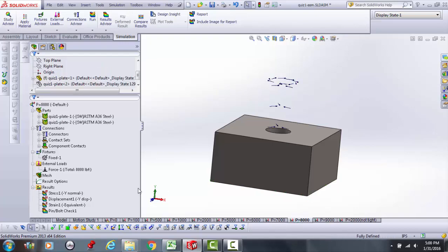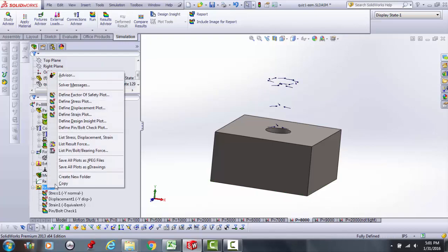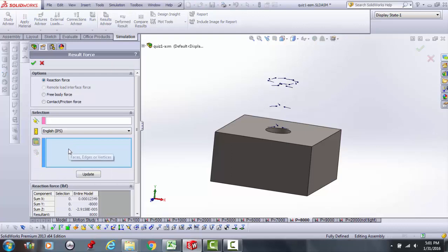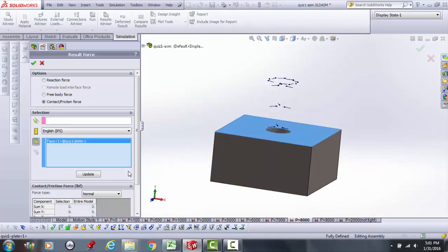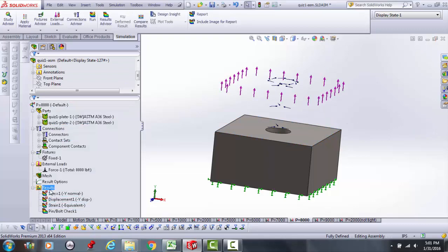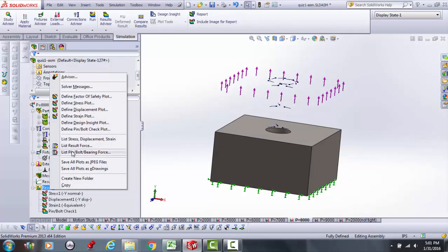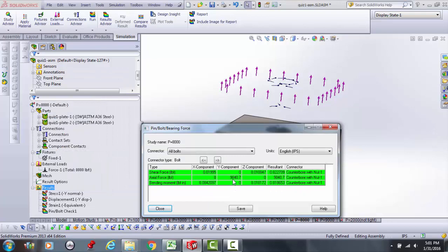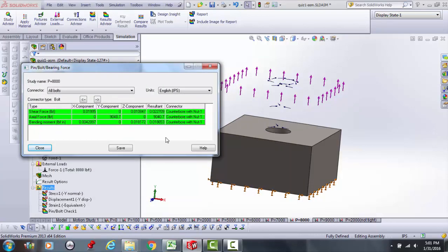And let's go to 8,000. Let's jump ahead. The others are the same. Contact force now for 8,000. So that's left me with only 1,000 compressive left on the members. So this is not right. Let's put everything on the members. Let's see what the bolt force is. Basically 9,000. It should be 9,000 plus 17% of 8,000. It's nowhere near right here.